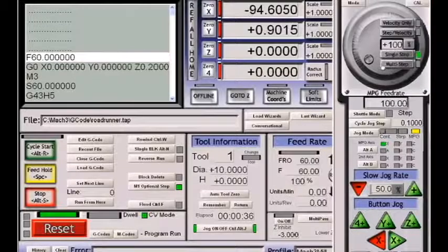Single step mode will move you one single step whenever you rotate the wheel a small amount. You must stop between steps to get single step to work. Multi-step, you don't need to stop. You can calibrate your MPG wheel, rotate it 5 clicks, and the axis will move an appropriate amount for those 5 clicks of movement. This percentage reading here is not used at the moment. It is part of the old step velocity mode, which will again be replaced.